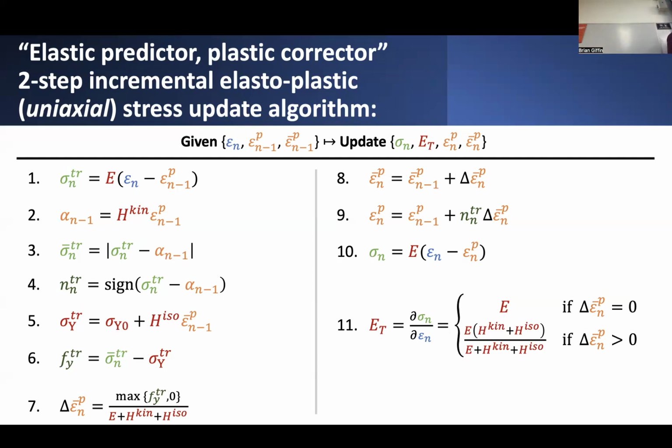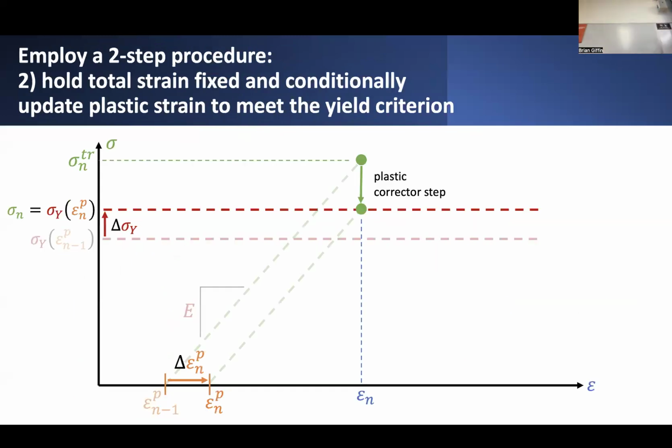And it turns out that you could just directly use this formula. In effect, this formula is taken from solving precisely for when going down this trajectory meets this trajectory of increase in the total yield stress in the material. So it's effectively just solving Fy equals 0 for the corresponding value of plastic strain that satisfies that condition.